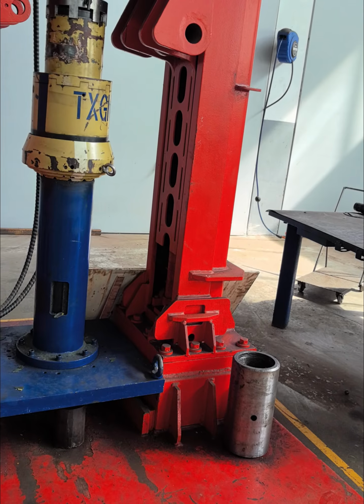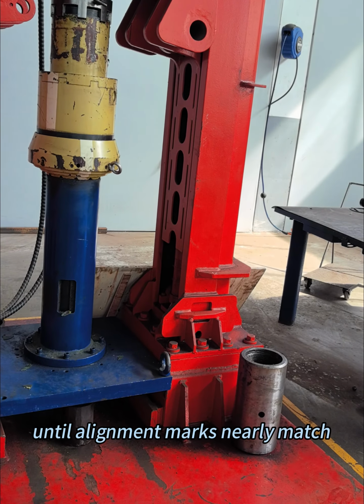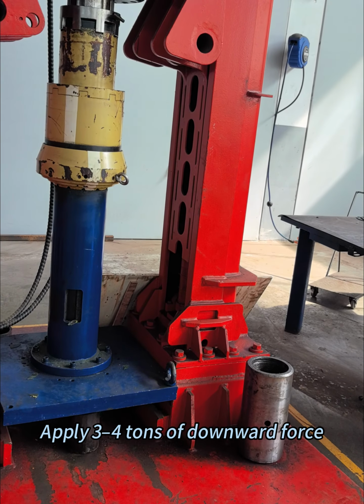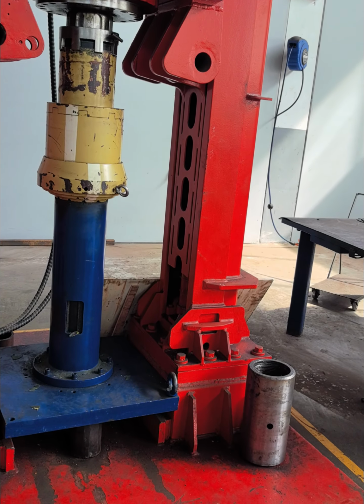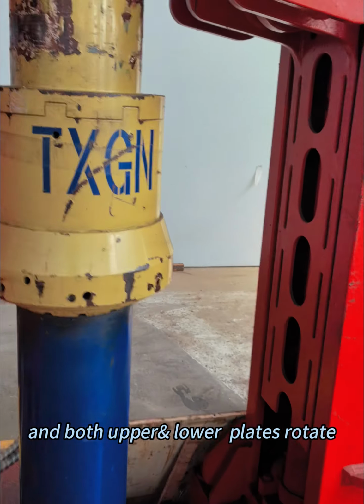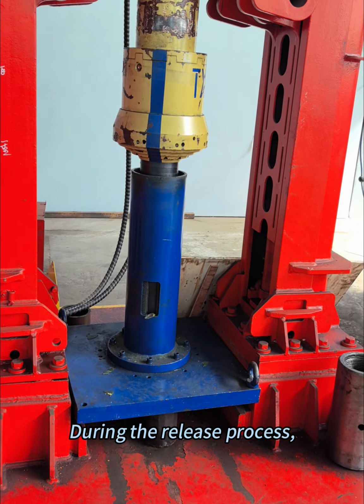Release. 1. Under natural suspended weight, rotate counterclockwise until alignment marks nearly match. 2. Apply 3 to 4 tons of downward force until the exposed part, the black section, is fully pressed into the anti-collision plate. 3. Continue rotating counterclockwise until marks align and both upper and lower plates rotate, indicating release.